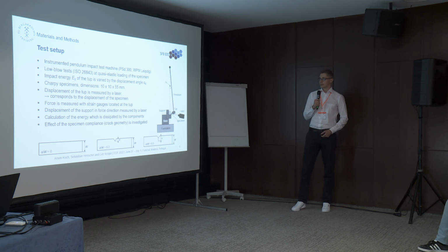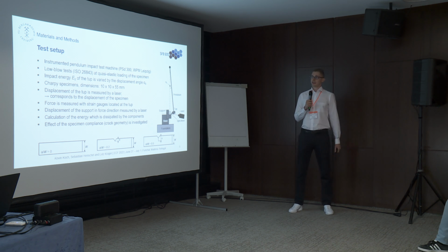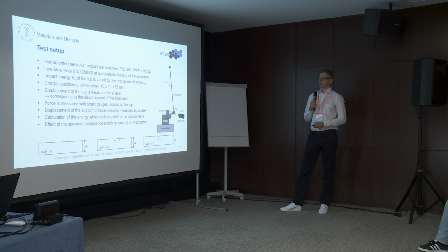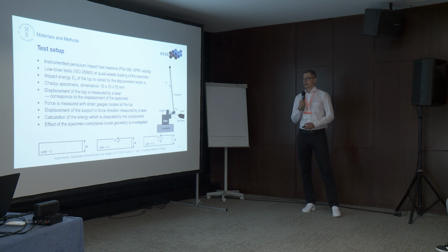So this is the test setup we used for our tests. We used an instrumented pendulum impact test machine. You can see the test setup here on the right. We carried out our tests in the low blow test manner and at very low impact energies to guarantee elastic loading of the specimen. The impact energy of the tup is varied by the displacement angle of the pendulum, alpha 0. We used Charpy specimens with the given dimensions for the tests, and the